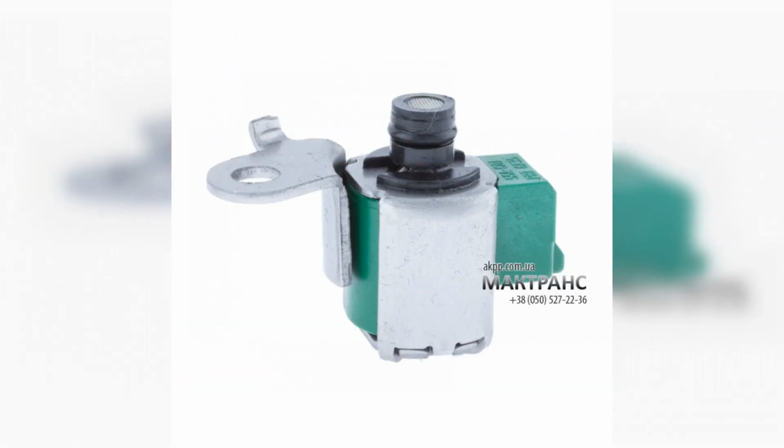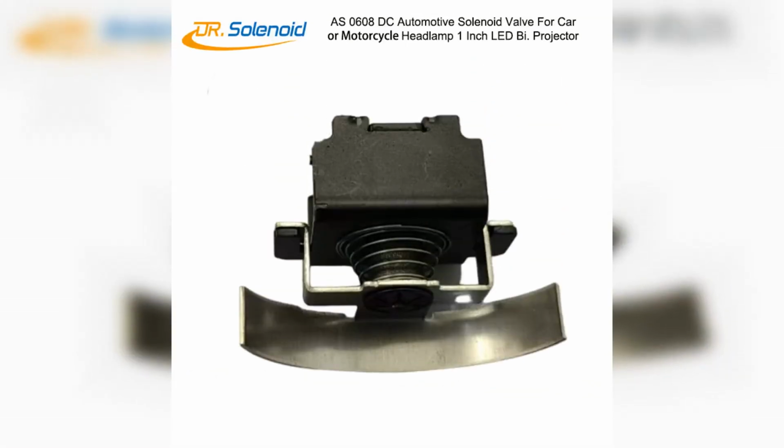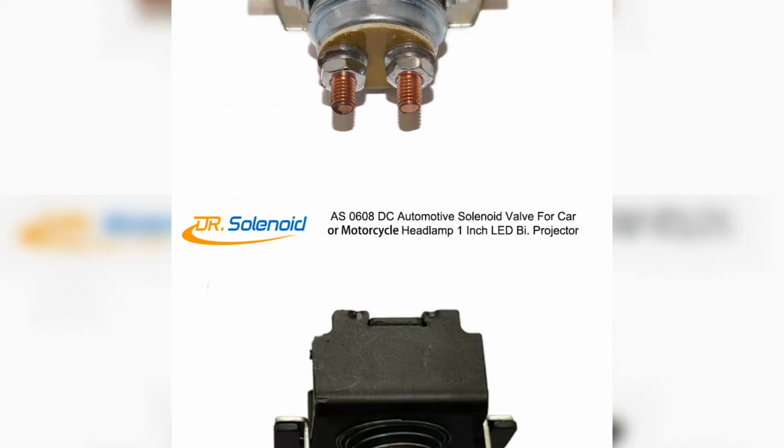How to eliminate or clear fault code P076C. Some suggested steps for troubleshooting and correcting fault code P076C. Change the ATF fluid and filters. Fill the transmission fluid to the required level. Flush to clean the internal transmission ducts. Check the connectors and cables. Flash or replace the PCM or TCM.